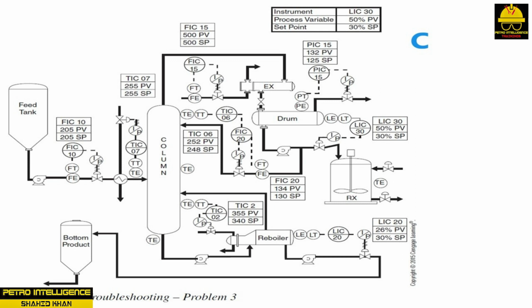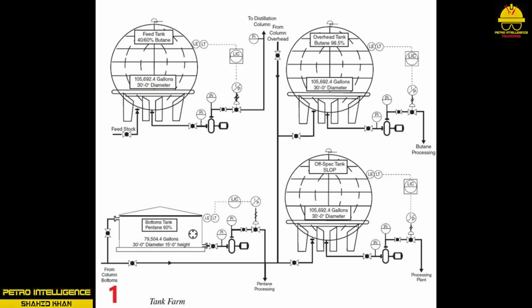1. Notify your supervisor and all concerned, i.e., engineering, maintenance, etc. 2. Ensure all safety hazards are secured. Trash, locks, old permits, etc. 3. Check equipment and instrumentation. Stroke control valves 0 to 100%, check lineups, etc. 4. Sample feedstock. 5. Line up feed tank to heat exchangers and column. Check each valve lineup. 6. Set feed tank level control to 50%, put in auto. Open feedstock valve to feed tank.